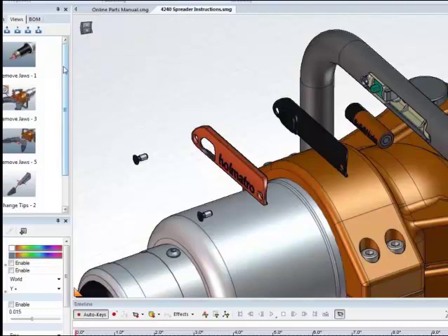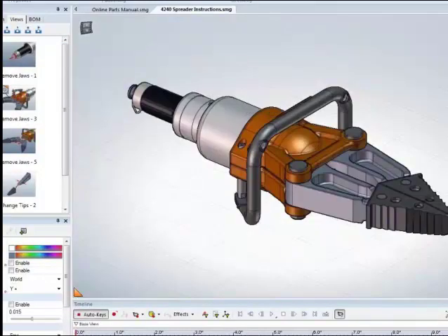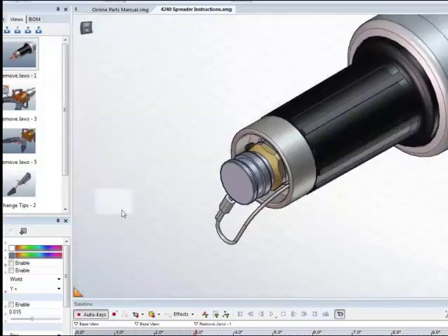By simply grabbing the views that I have in my Views tab and dropping them on the timeline, what I'm essentially doing is setting up an animation. Now, I like to always grab the same view and drop it in a couple of times, and that means nothing's happening between each of those views as I drag this time bar around. But if I then go ahead and transition over to, say, this view, let's go over to about 3 seconds there, maybe go to about 3.5, and then I'm just going to continue to drag views onto the screen.